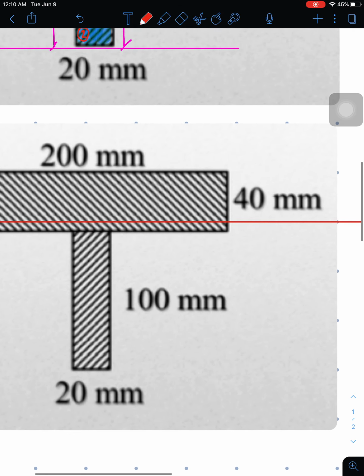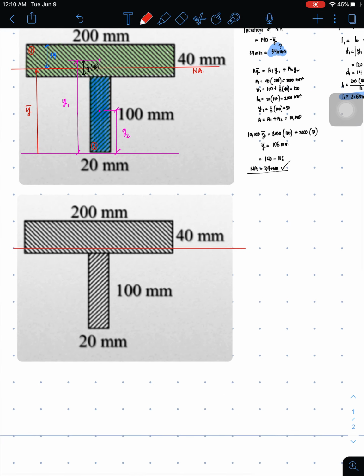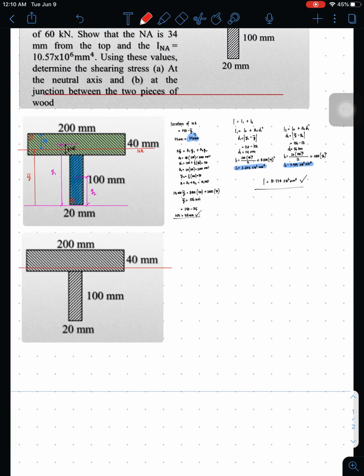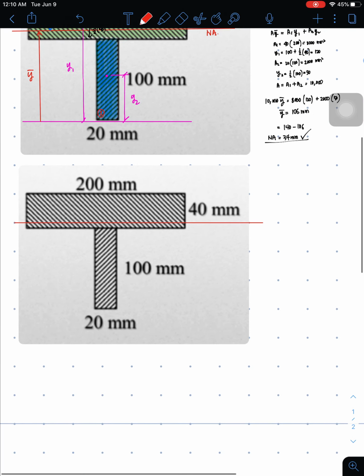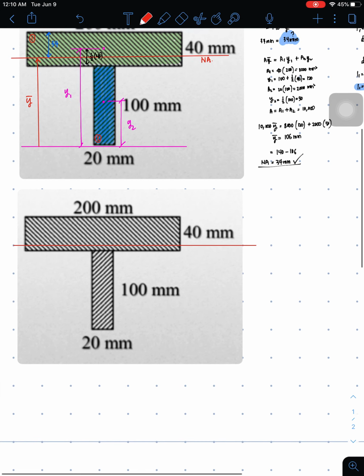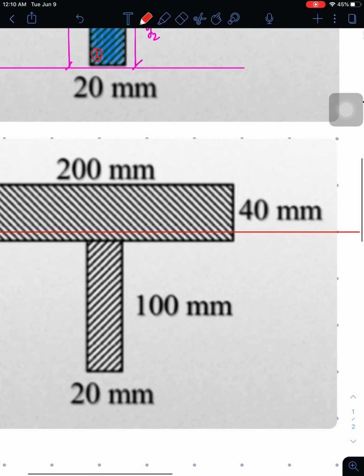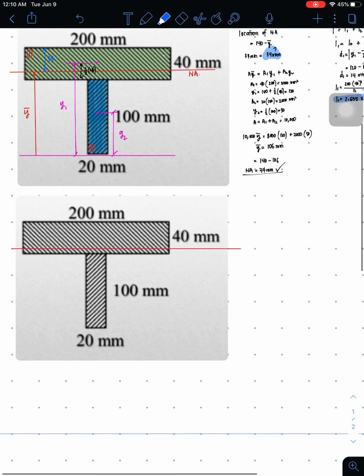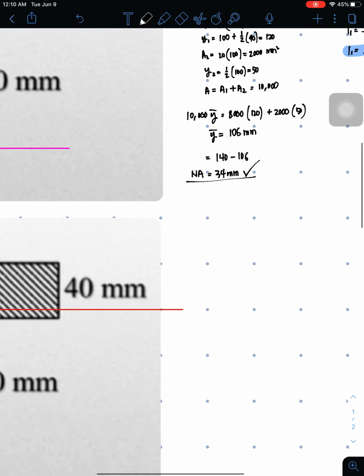So it is made of different materials, connected together. It is not monolithic, not made as one piece. They are joined together. So we're going to check where the largest stress is. But for the meantime, we're asked to find the stress here at the neutral axis. So basically, you end up with two areas to consider. That is why we talked about area because of this.